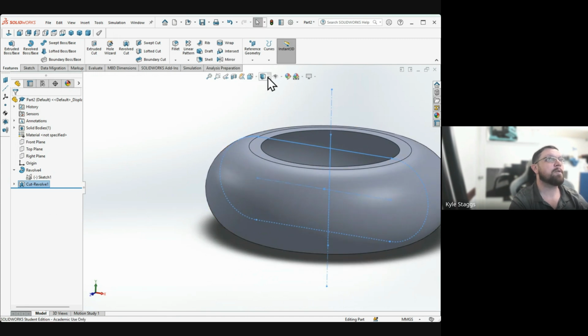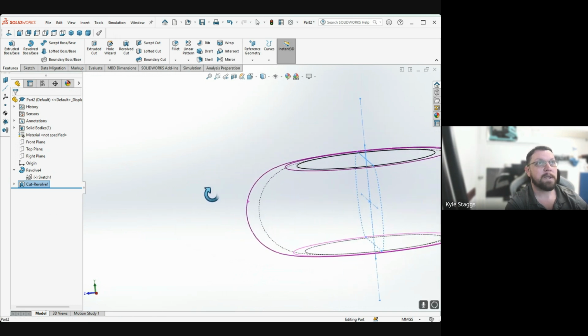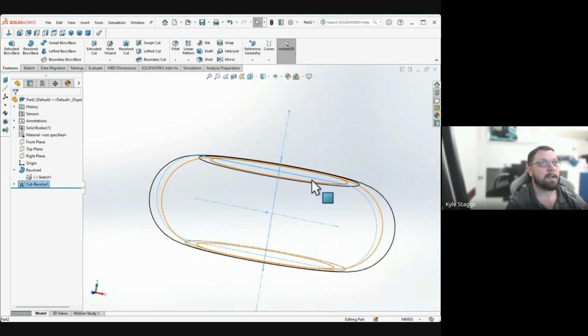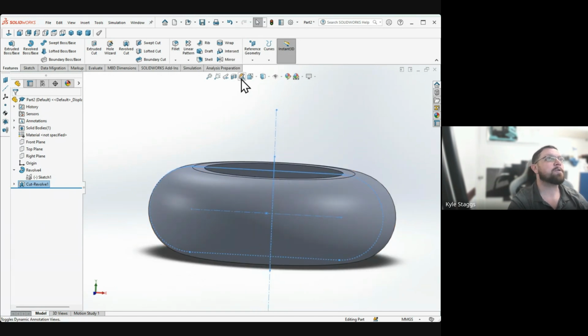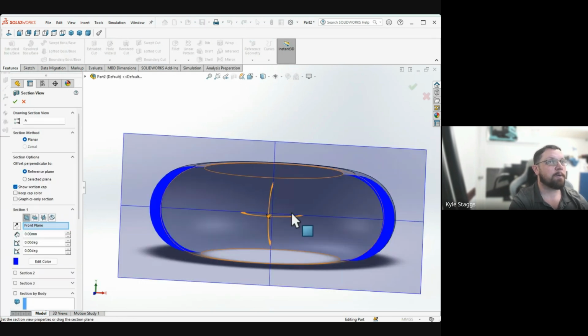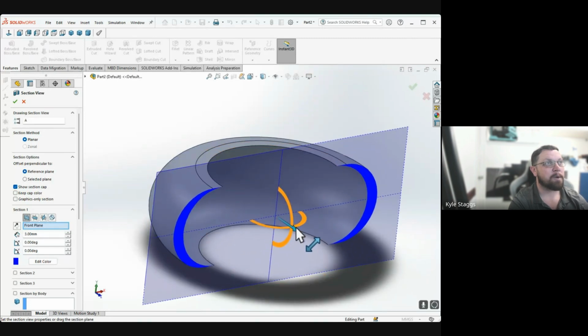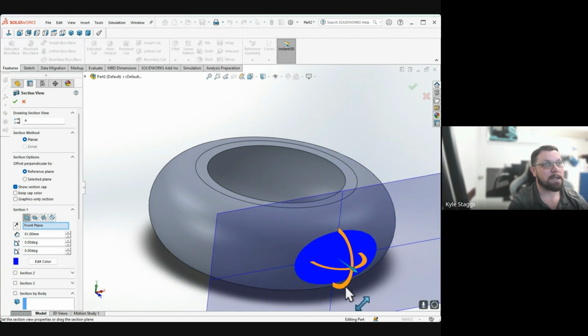So if I go to view, I can view this as a wireframe with internal dimensions. So this thin region, I've now made effectively one layer of an onion almost, right? An easier way to view that is to go back here to have all of the edges and do another view trick, which you'll use later, called a cutaway. In a half cutaway, you can see, as I pull this along, what that region looks like. So it's basically the skin of an onion.